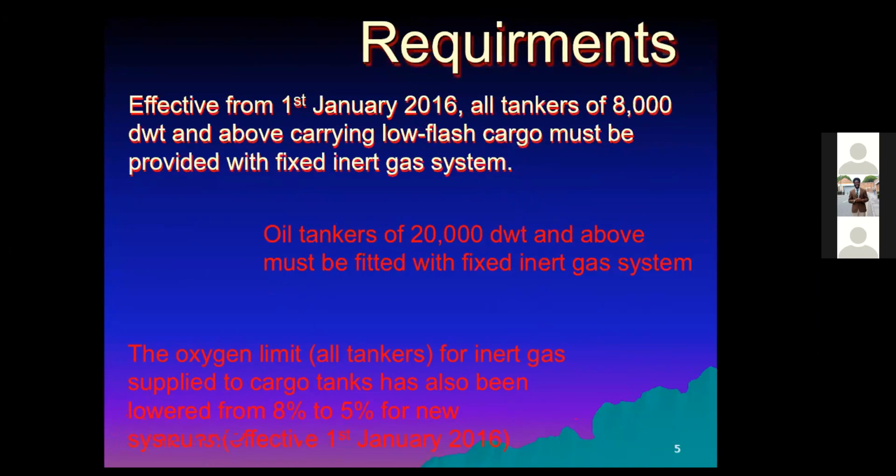Okay, so there are some changes, like I said earlier, that have happened when it comes to the requirement of inert gas system. As you are all aware, and this question does come up in orals, with effect from 1st January 2016, all tankers of 8,000 deadweight tonnage that carry low flash cargo, that is below 60 degrees C closed cup test, must be fitted with inert gas.